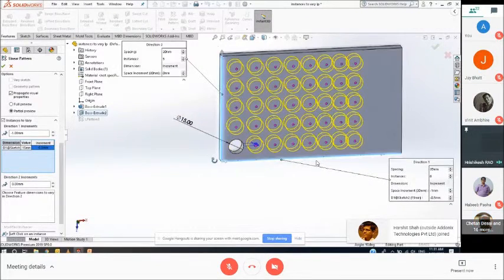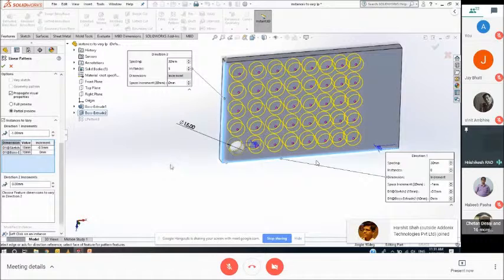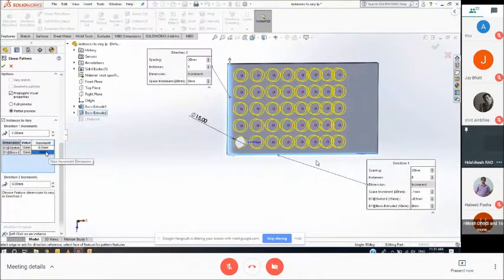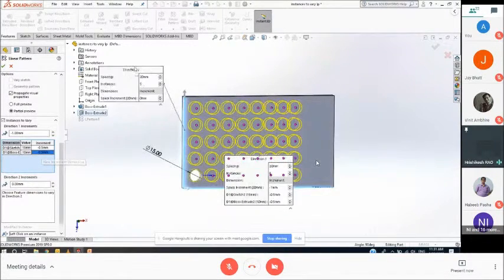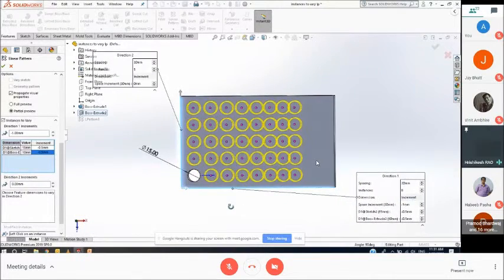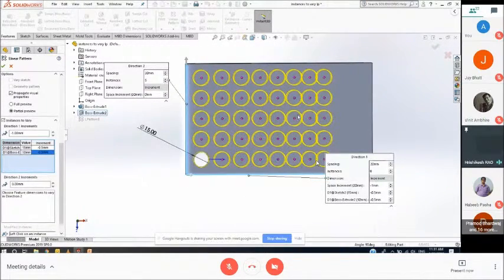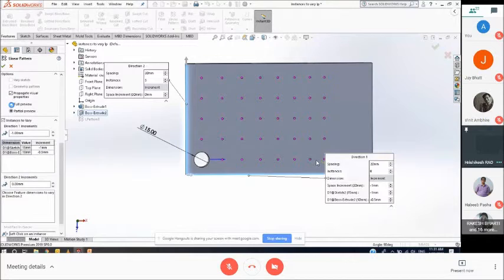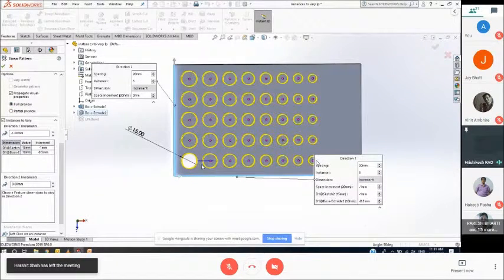And similarly, I'll select this depth option, the depth of cut, and again I'll specify minus 0.5 mm. As you can see that change in the preview section, as the pattern goes on, the diameter is being reduced. For better clarity, I'll set this increment to minus 1 mm. Here you can see as the pattern goes on, the diameter of the pattern is being decreased.